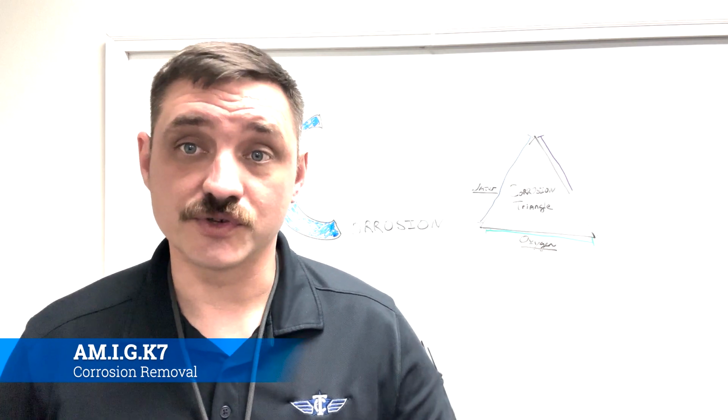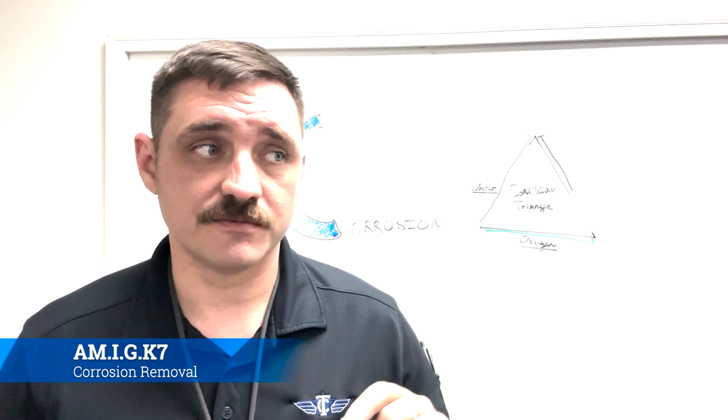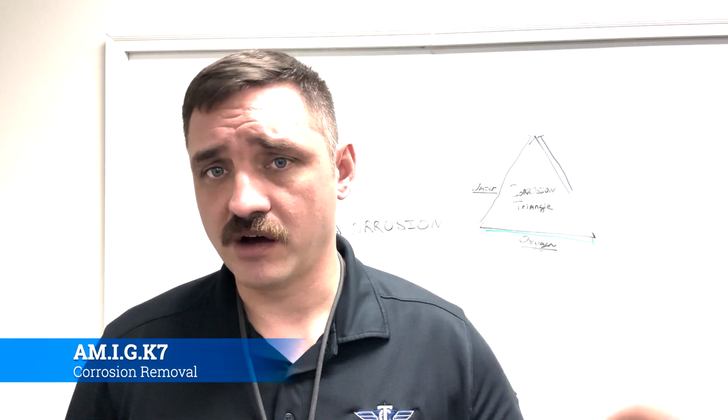I only really delve into the let's try to correct the metal and restore the metal modality if it becomes cost prohibitive for you to do it. So for instance, on my airplane on the left hand side, inside the inspection panel, there's some corrosion on the spar. Well, it's not really that big of a deal, and so we just took it off with some sandpaper and then shot it with some CPC and called it a day.